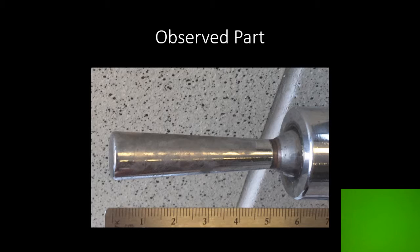Firstly, some pitting corrosion is in evidence on the ball portion of the handle. There is also uniform corrosion occurring at the point at which the handle joins the ball. Lastly, there is mechanical wear occurring along the handle where the part is normally grabbed.